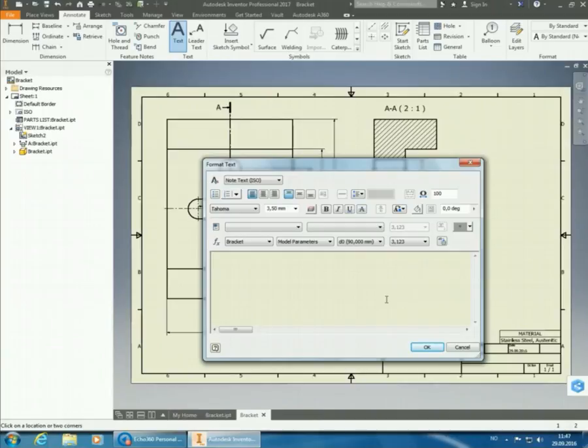Like when I worked in Emenco, we had a special plugin module to our Inventor, so that when we were in the 3D model, in the properties part, we could set the tolerances there, so medium and K for the geometric ones, for an example. And then it would automatically fill it in the notes field that we had here for general tolerances. So usually there are more automatic ways of doing stuff when you're out in a company. But those are usually custom made for that company, so that we can't really show them here properly. So instead we have to do everything by hand.